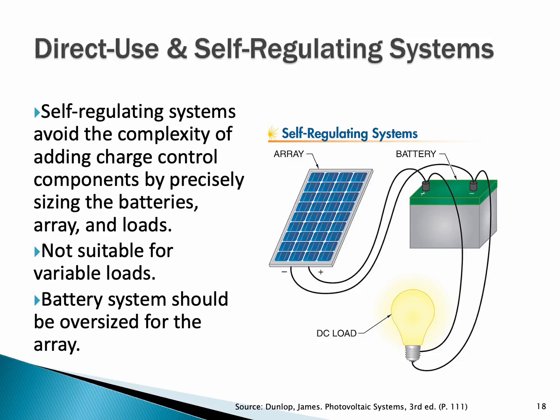So it's a really closely sized system. The battery will be depleted or nearly depleted by sunup, and then the array has to be large enough to power up that battery throughout the day. The reason for these tight parameters is weight and expense. So the battery is just enough to power up the light during the evening time, and the array is sized to power up the battery during the day, just enough.